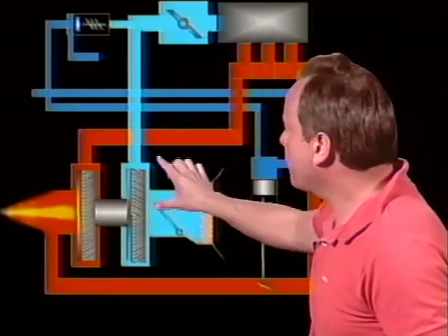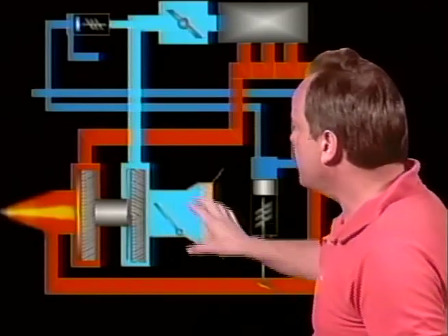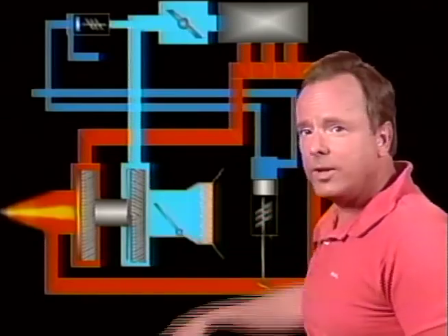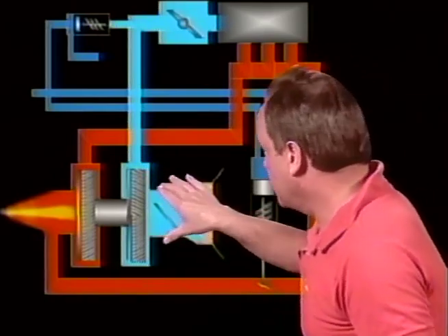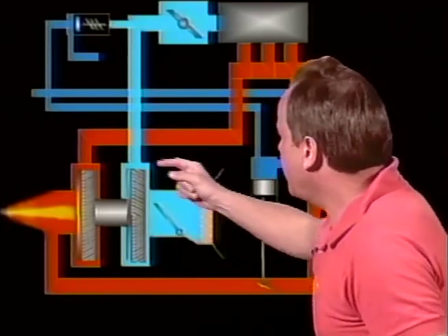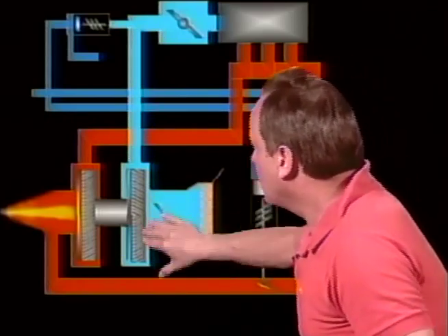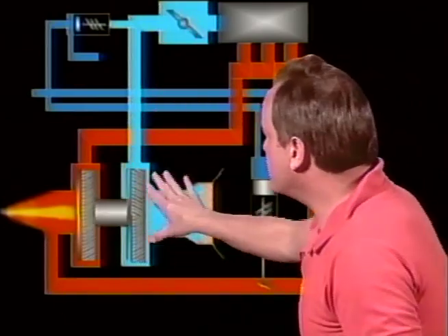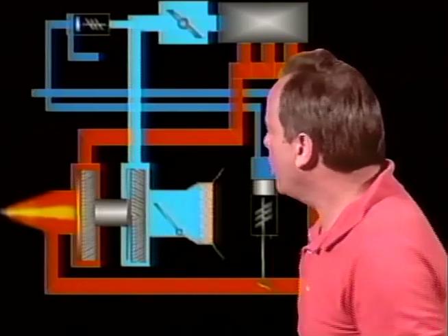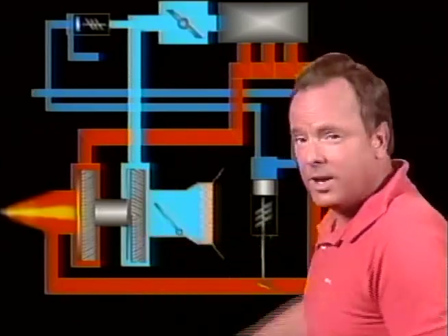engine. But the difference is the way a supercharger impeller or compressor is driven, and it's generally driven by being connected directly to the engine. We'll say the crankshaft or the camshaft of the engine, so it's connected directly to the engine with a gearbox in between, and that supercharger then compresses the air, but instead of being driven by exhaust gases, it's driven by the engine itself. Sometimes they'll have a gearbox on a supercharger, so you can select either high-speed or low-speed